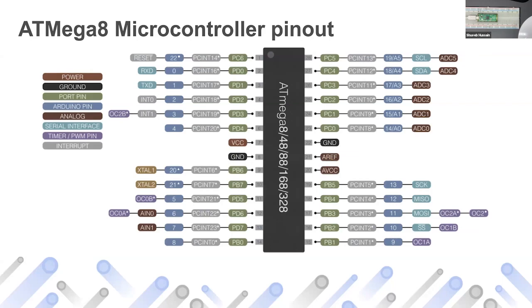So I was just telling that microcontrollers have both RAM as well as flash memory. In flash memory, your program sits and runs from there. And then in RAM, of course, you can have your variables and stuff like that, right? Of course, you don't need to specifically worry about that when you're running a program. The compiler generally takes care of it. And also when using a microcontroller, usually you do not use an operating system, right? You're running on bare hardware, on the CPU straight away, right?